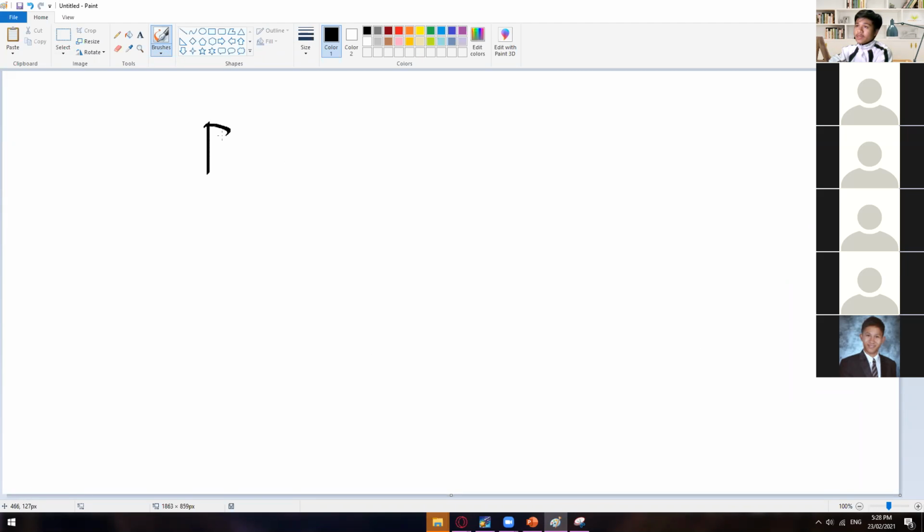Anyway, we have this formula, P is equal to E times I, right? We need the resistance, where E is equal to I times R. From here, we can replace this E with I R, which will be multiplied to this I. In that case, we'll get I squared times R. The one that we're looking for is the value of your R, so just transpose this one below.